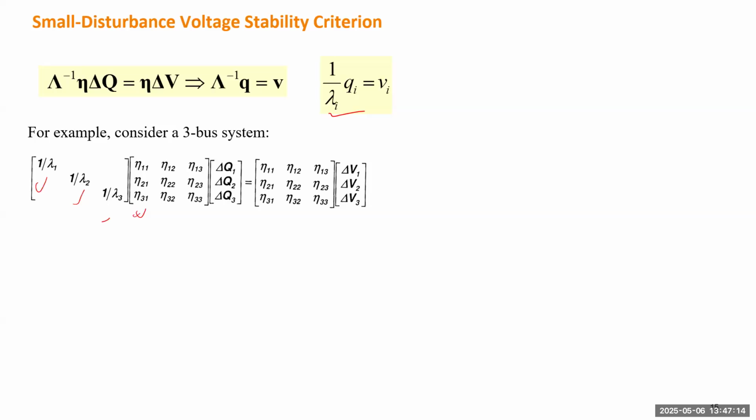For each eigenvalue, you solve the eigenvector. And you make the 3 right eigenvectors into a 3 by 3 matrix. That will be the matrix eta. Using that eta and its inverse, you can diagonalize the regional Jacobian into this matrix of eigenvalues. So this one will be the same as that general equation.